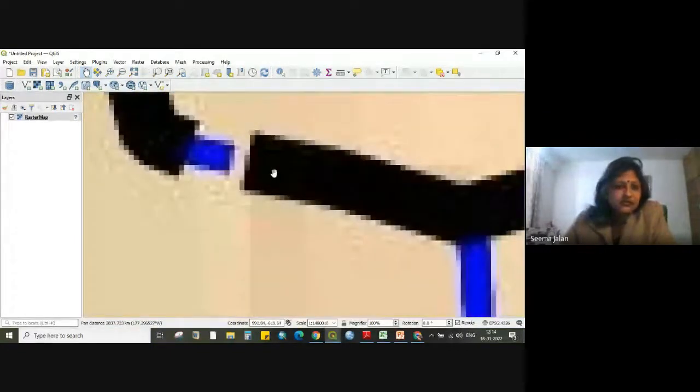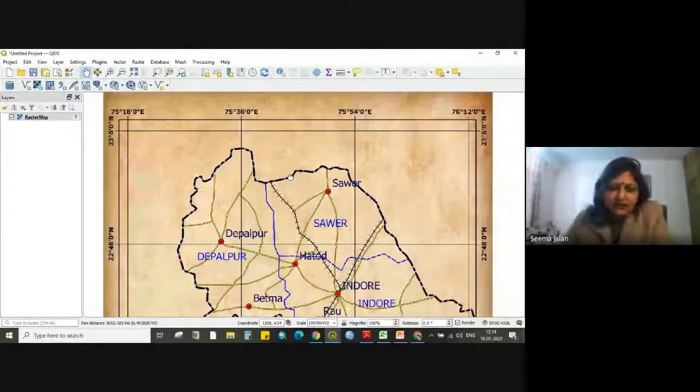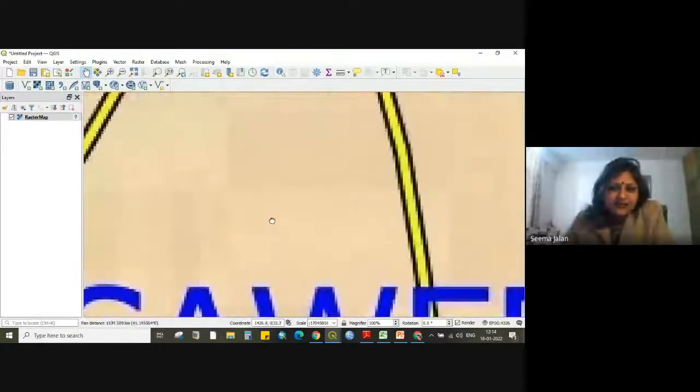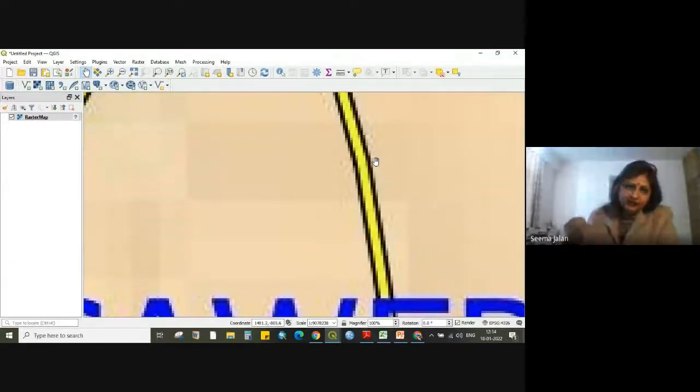These pixel values are filling this mesh. We call these values intensity values, DN values. Just for understanding, I can say that this raster is like a mesh in which there is a grid, and in that grid we have pixel values filled in.